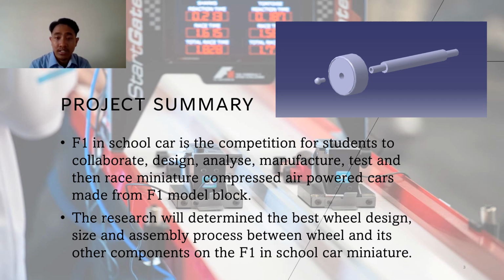Based on the analysis of the formulation moment of inertia and resistive force of rolling friction, all the important criteria in designing the best wheel can be achieved. The targeted time for the miniature to reach the finishing line is 0.98 seconds. The polylactic acid will be used in designing the wheel as it has good mechanical properties such as high hardness that can hold the total load of the car from static condition to dynamic condition.